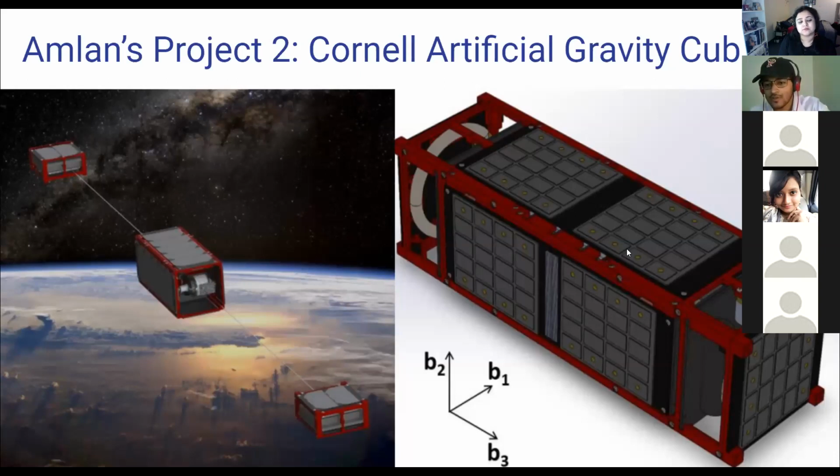What I worked on is the solar panels that you see on these two sides, if you can look at my mouse. There are many solar panels on the two sides, and we had to keep these solar panels pointed towards the sun, because the power that you get for the spacecraft is obtained through the solar panels. That's a very hard thing to do. That's not trivial, because you always need to make sure that the spacecraft points towards the sun, while making sure that if you have an imaging system on board that is pointing in some direction on Earth, that still points in that direction. Meaning the camera is looking that way, while the solar panel is facing the sun.